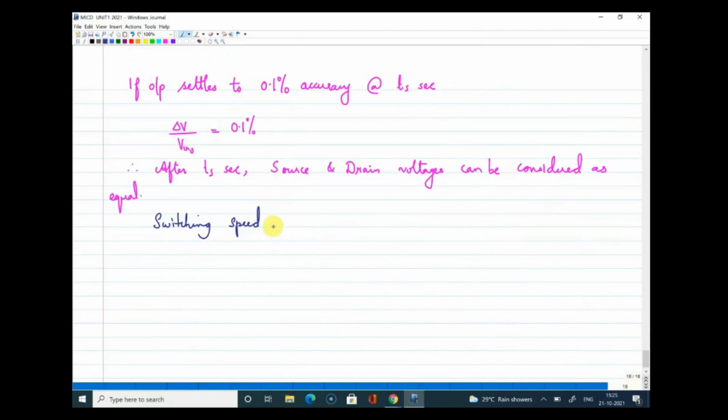So, the switching speed is basically given by two factors. One is the R value. Yes, the time constant of the circuit, that is correct, and the value of the capacitor, that is true. So when I say R, what is this R? This R is actually the on resistance of the switch. Since this is on resistance, we'll mark it as R on, and it depends on the type of switch that we use. If it is an NMOS switch, we'll write it as R on N or R on P, and so on. This is one factor.